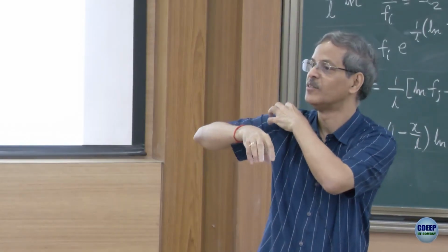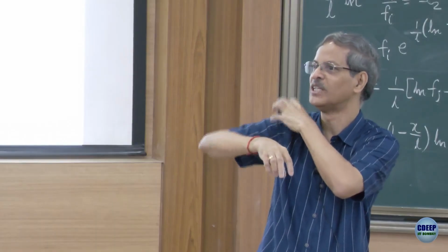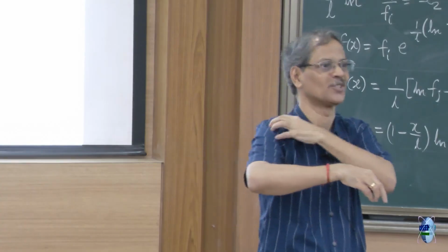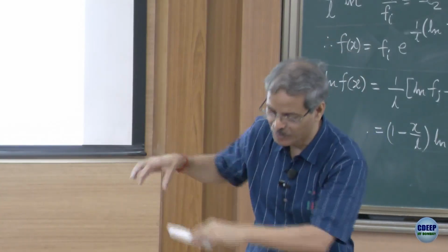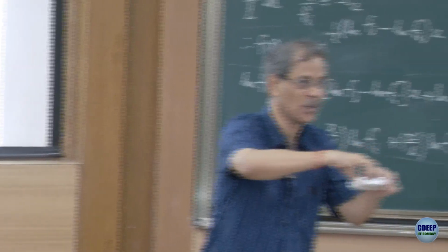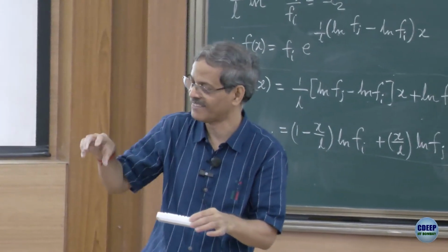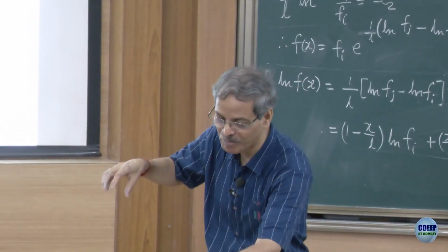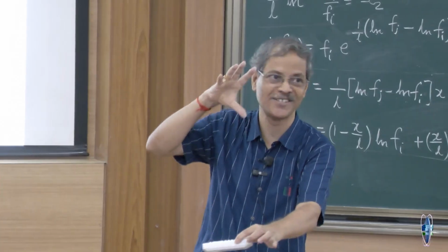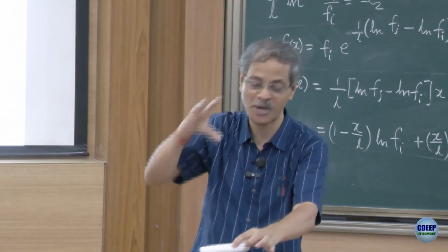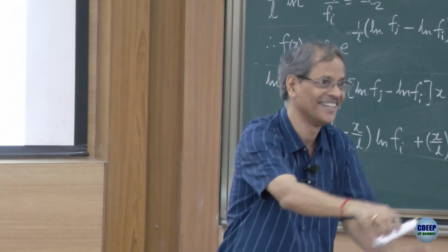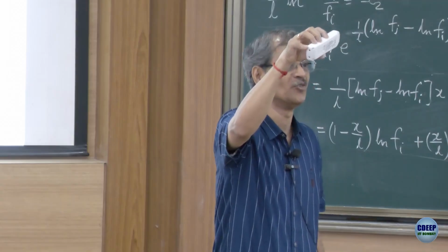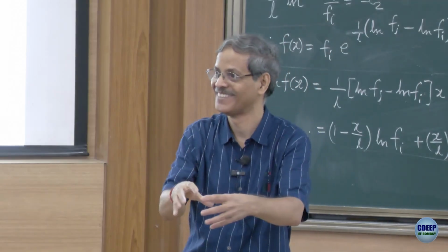So, the joint coordinate frame, you need to get what is the input I need to give to the motor to get some velocity. So, first this is the belt, conveyor belt is moving like this. So, I need to get the tip, the gripper end effector of the robot should approach this particular point in the capital XYZ coordinate frame, global XYZ coordinate frame with a particular velocity in that direction. Then only I will be able to pick up that object, only when these two velocities match, right.